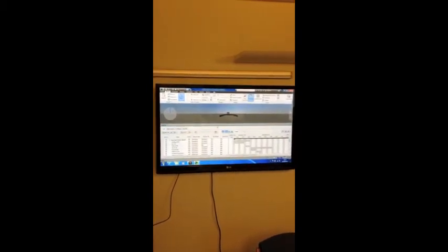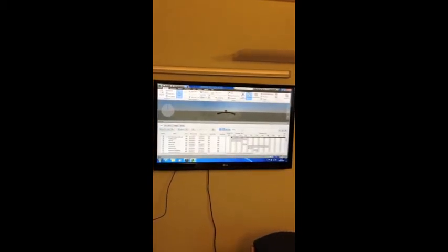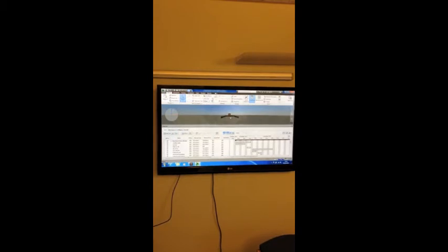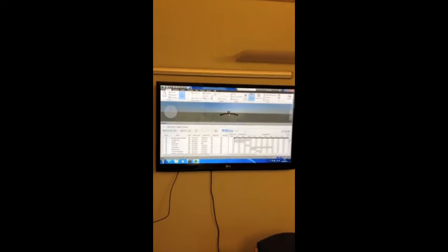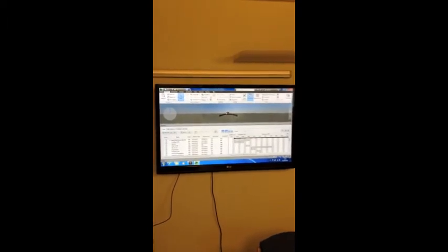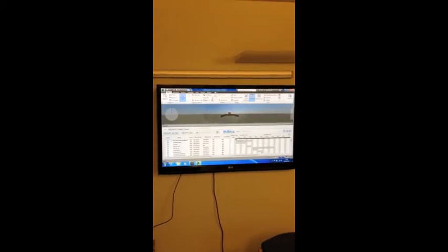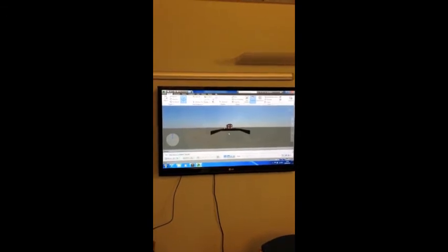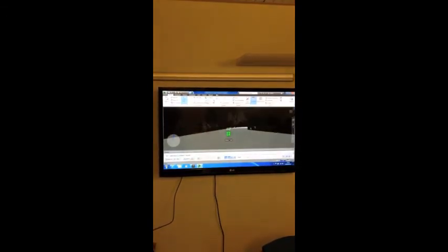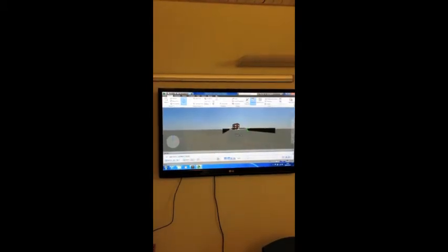Okay, the next step in the process now is to commence linking the tasks in your programme to each of the 3D objects in the model. And there's a few ways which this can be done, but we're going to go through linking each of the objects manually using selection sets. So if you just minimise the timeliner for the time being so that you can see the model better, I'm going to show you how to create selection sets.